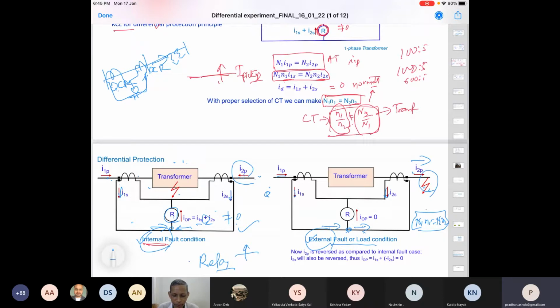If there is a communication link failure, then there is a problem. These are the limitations of any system; any principle you tell, there is a pros and cons. What you say is correct. This relay will not be able to identify external fault. But from the protection principle, that is not a requirement. From the backup principle, if this breaker fails somewhere here, then the following things will not be a problem. That is a generic problem.